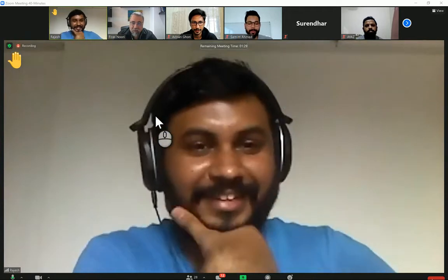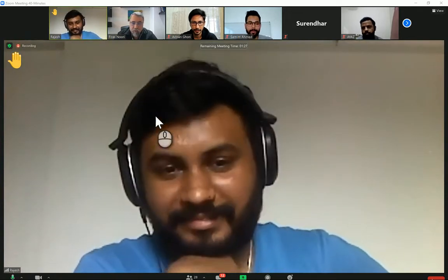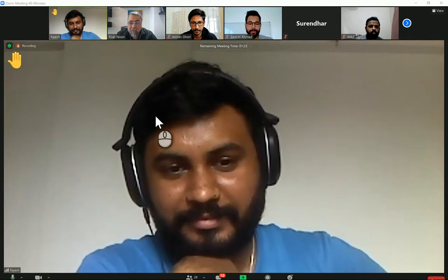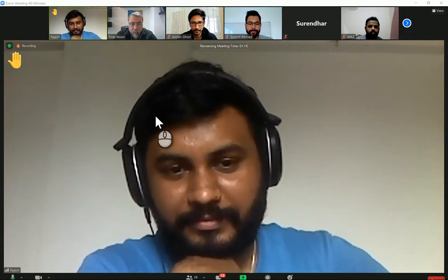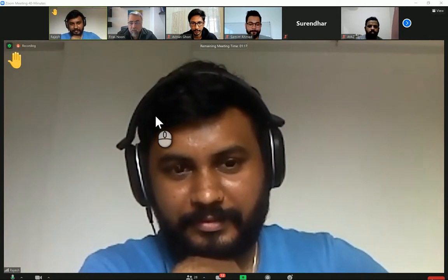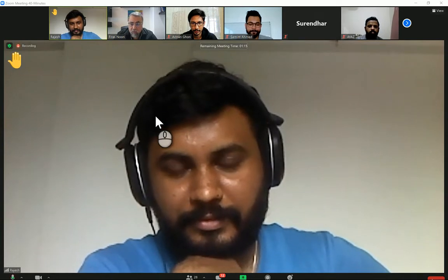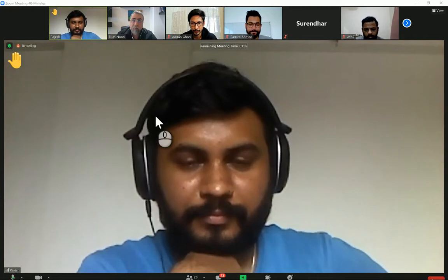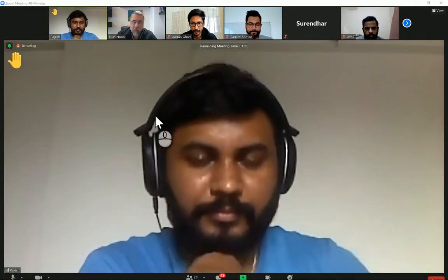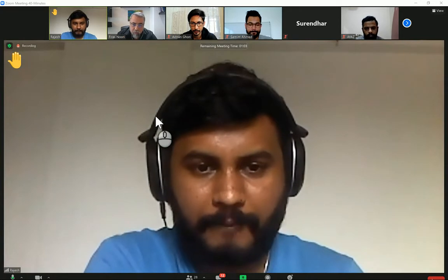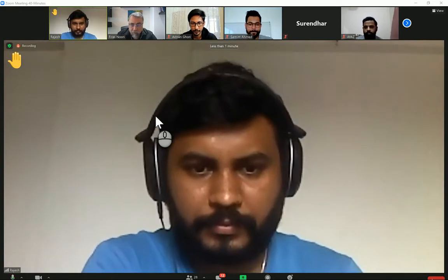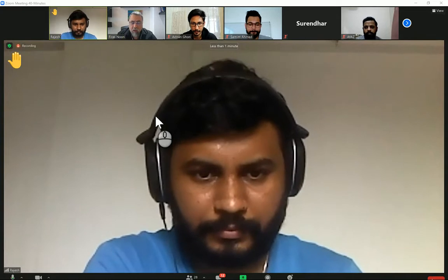You just create your geometry, the complex shape, in Rhino. Don't send the object to the Revit project environment. Just send it to the conceptual design platform. Then open a new Revit file and save as, or import the conceptual mass into Revit. If you go to my YouTube channel, my Revit course that I teach at Ajman University explains in detail how you change from conceptual mass to the Revit project environment.